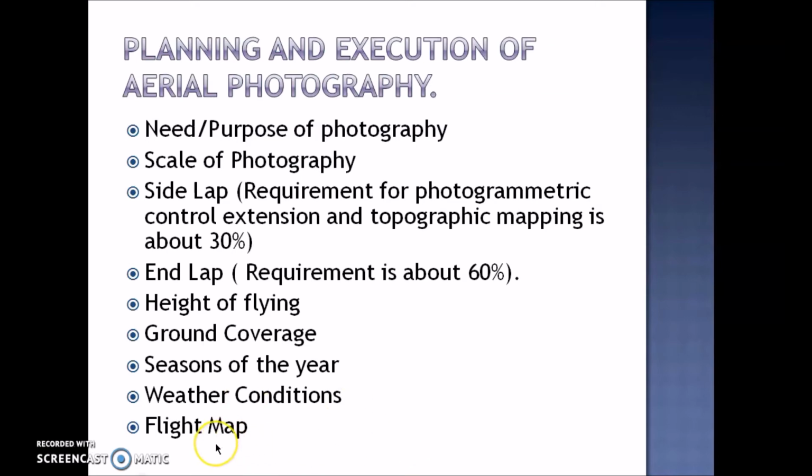And the last one is flight map. The flight map is prepared depending on the considerations and specifications which are mentioned above. All the above parameters will be considered to check out this flight map. The flight maps are prepared to obtain the project boundaries and flight lines the pilot must fly so as to achieve the aspired coverage. The flight map will be designed so that all the above needs to be covered.